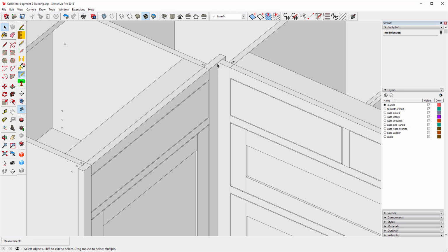And of course, you don't know exactly whether these are going to be perfectly level. That depends on the floor and what have you, and how well you've leveled your toe kick. So there's a little left over here just in case there's something you need extra material to account for some unlevel or unevenness.